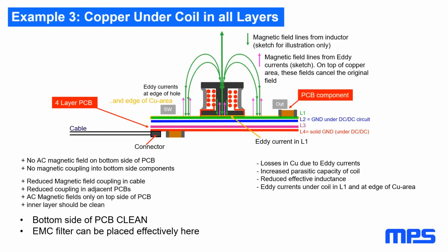In 99% of the cases, it's always the best approach in a multi-layer PCB to reserve at least one complete layer as ground, and don't do routing in it, and avoid close density vias with keep outs that create cuts in the ground plane. And from every block you have, you use vias to make the reference to the system ground. This is a safe way.